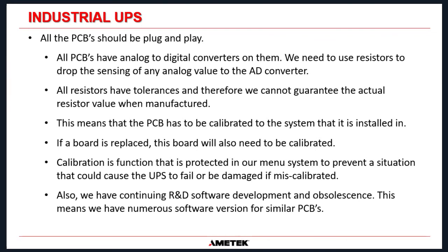Now, the issue that we have is all resistors have tolerances. When you go to a resistor manufacturer, they will say, okay, this resistor that you're buying has a 1% tolerance. And what that means is if it's a 10 ohm resistor, that will be 0.1 ohms high or 0.1 ohms low. It's not going to be guaranteed to be 10 ohms. And if it's a 5% tolerance, it's going to be half an ohm. The value that it can change goes up.